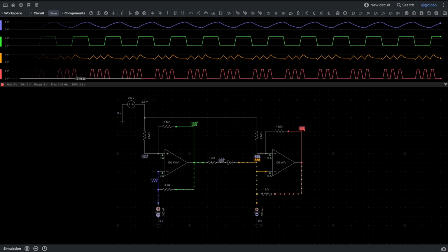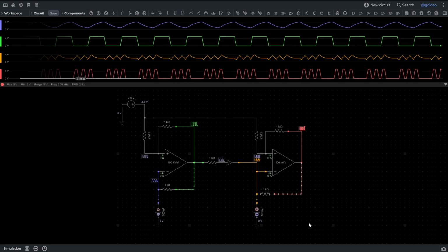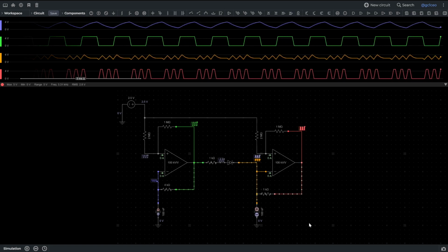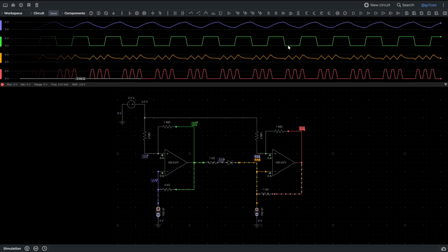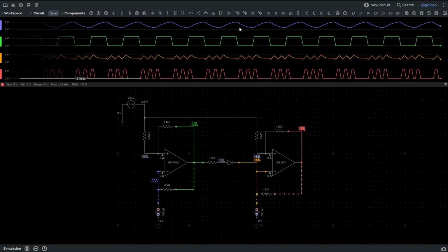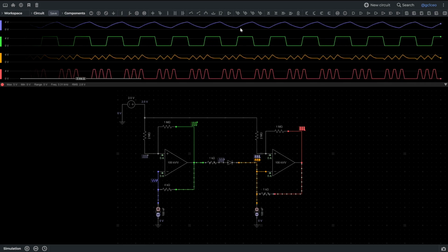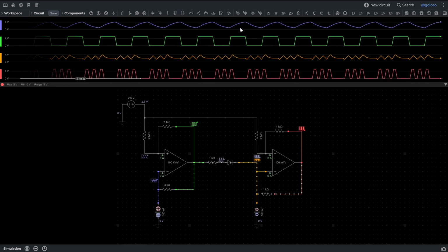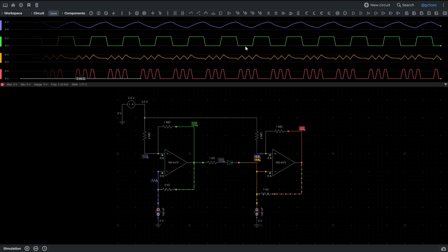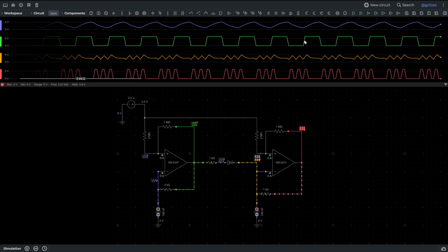Now, this is another weird example I made a while ago, and I can't remember why I made it. I think it was just for different waveforms. But yeah, it does a Schmitt trigger in two different places, on two different waves. One's a loose sawtooth, and it converts it into something that's sort of a square wave.